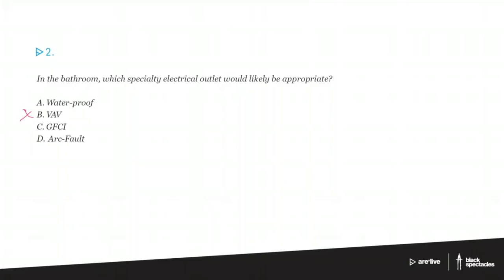And if there happens to be linens nearby or curtains or something like that, it's a big fire hazard. In recent years, most of the codes have picked up having arc faults in bedrooms and potentially in living rooms, places where people might be sleeping. I don't know if that's the technical response, but that's the way it was always explained to me.